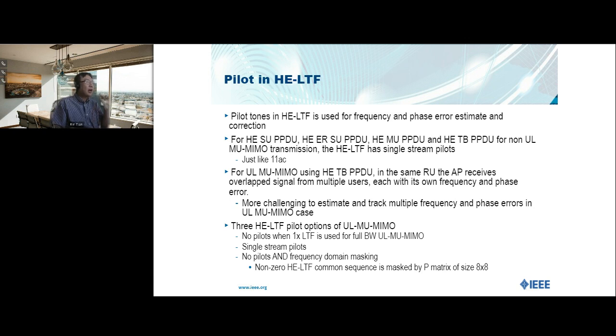So because of that, there is some special treatment for HE-LTF pilots for uplink MU-MIMO. For example, with the 1x LTF used for full bandwidth uplink MU-MIMO, because the LTF is so short, the phase drift will be small. You will not use pilots. Or you can use single stream pilots, just like the other transmissions.